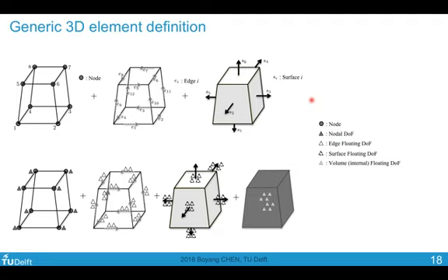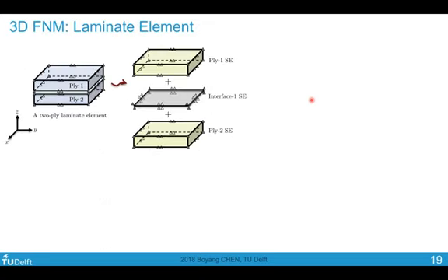And you can make use of these pre-allocated degrees of freedom to tailor your element to a specific application. So that depends on the characteristics of your material and whether you expect to have a T-crack junction or some channeling cracks intersecting each other, then it's up to you. And here I'm going to demonstrate the application of this method in a composite laminate, where I expect to have different orientations of matrix cracks on top and bottom plies.